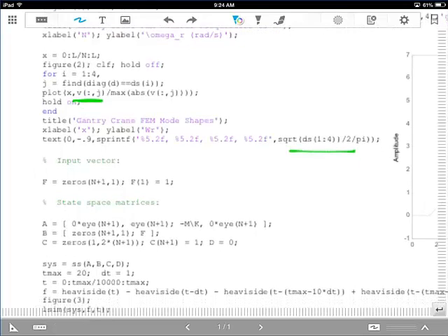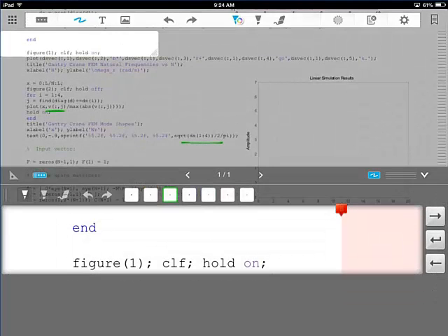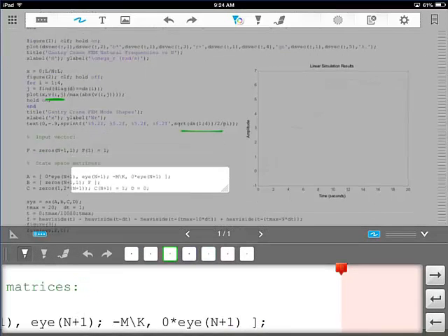And then we want to actually solve for the response. So we want to convert this over into a state space form, because that's what we do when we want to do a simulation. And we're going to put a force into the gantry and then look at the response of the payload. So we could look at the response of the whole cable, the whole system if we want, but in this case, let me see if this is a little better way for you to see it on the screen. It's a little easier to write.